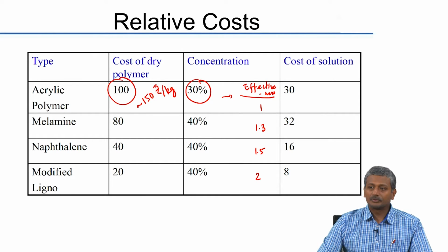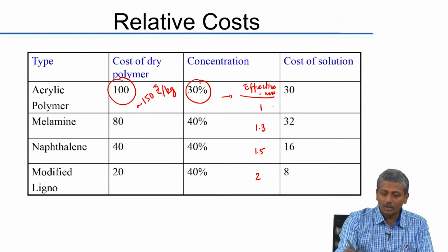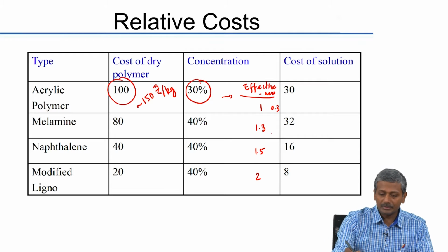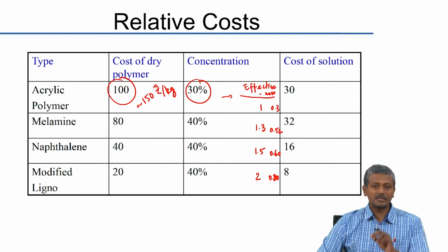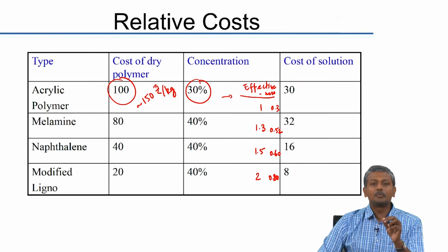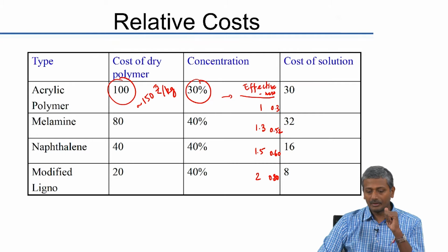So, convert that 1% to the actual amount of solid content that is actually required. We are talking about 0.3% of the solid, right. Here it is about 0.52% of the solid, here it is about 0.6% and here it is 0.8% of the solid superplasticizer. That means the effective solid molecules of the superplasticizer that are required to produce the same degree of workability in the concrete.